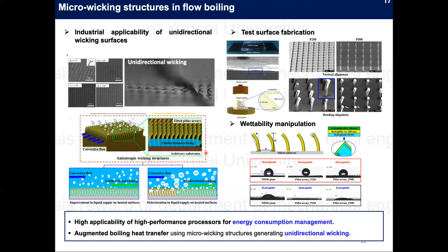And therefore, these structured surfaces are expected to enhance the heat transfer by generating unidirectional wicking to augment the capillary driven force when the liquid propagation corresponds with the pillar tilt direction. And please look at the graph on the right.